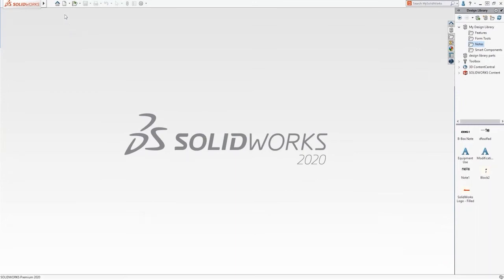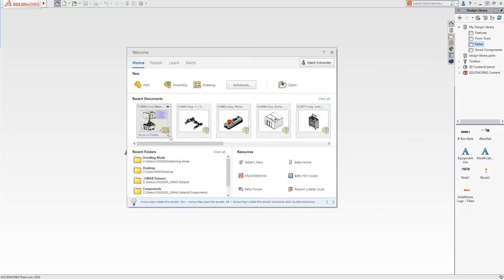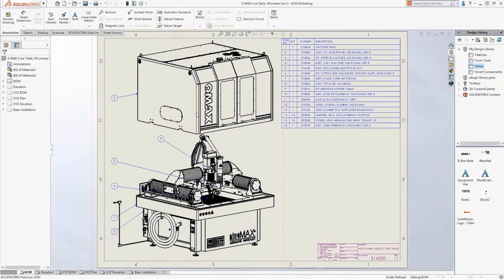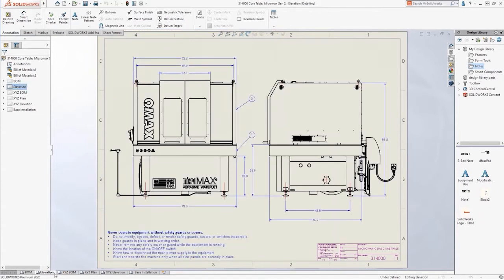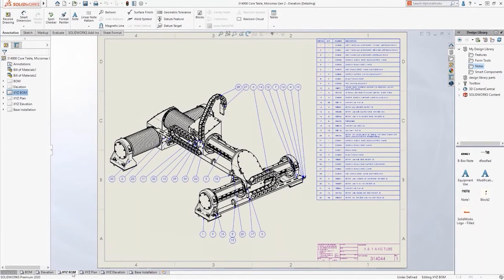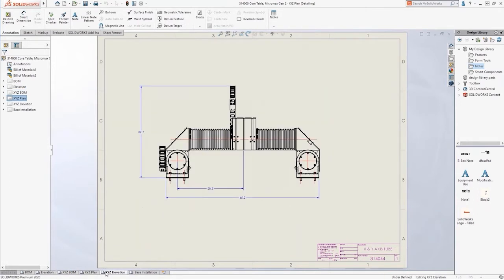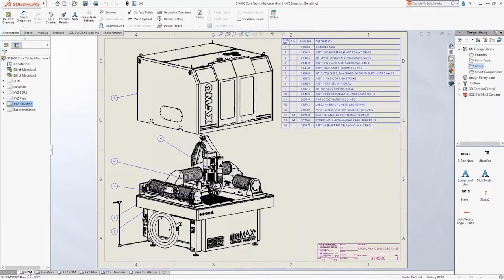So once again, you want to make sure that you're opening your design with that specific mode selected. So we want to make sure that we're selecting detailing mode. From there, the drawing is going to load lightning fast. As you're going to see here, as we switch between the different sheets, that is also going to happen very quickly. And this is because only a very small amount of the data from the model is actually being loaded. Primarily, this is just loading graphical data into our SOLIDWORKS session.